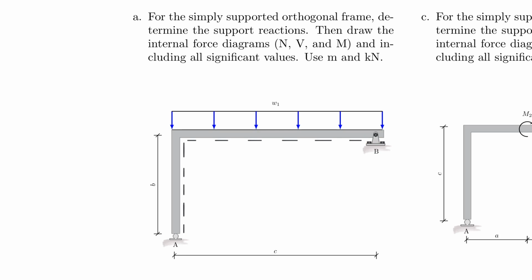And then please remember something I showed to you in this lecture, that the diagram for this vertical column is different or separate from the horizontal beam. So sometimes I see students who try to make a connection here from the diagram of the vertical member to the horizontal member, but you should really look at them separately, and I believe I have shown that to you throughout the lecture. So please pay attention to that.